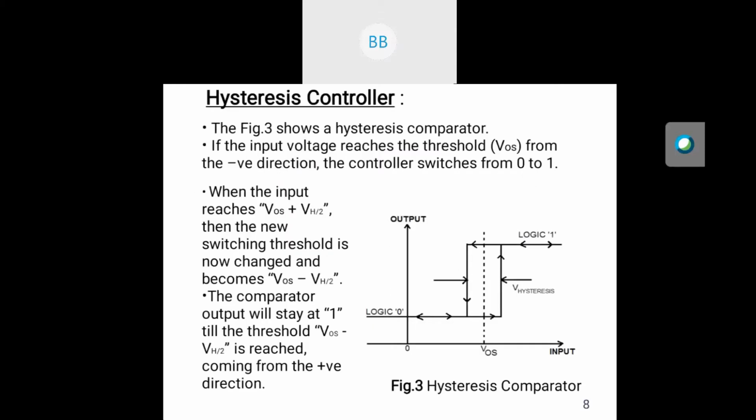Hysteresis controller. The main role of hysteresis comparators is to determine whether an increase or decrease of flux or torque is required or not, depending on whether the torque or flux errors are outside the hysteresis band or not. Hysteresis is important for producing stable switching behavior in a comparator circuit. This hysteresis is aided by including a positive feedback loop between the output and input.